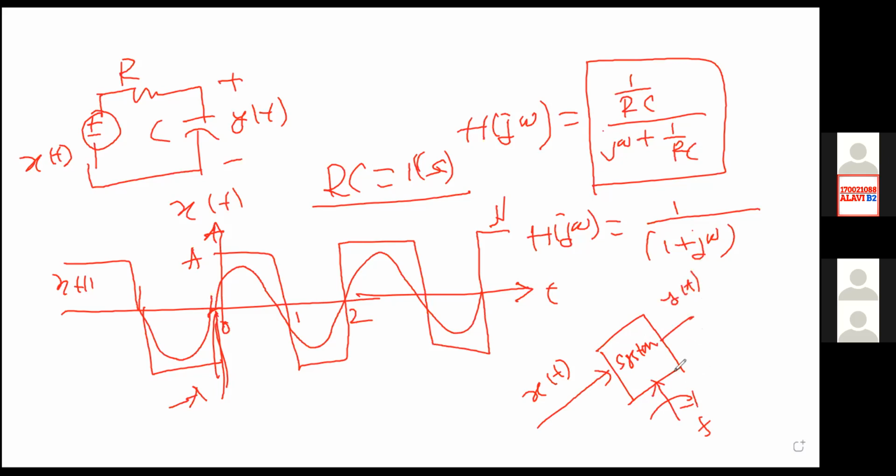If your system is tuned to frequency f0, then what will happen? You will get the fundamental sinusoidal wave, isn't it? Now, if your system is tuned to 2f0, and the 2f0 frequency exists in your signal, you will get an output sinusoid with lesser amplitude. Similarly, you can tune to 3f0 and again observe the output. If that harmonic is present in your signal, then you will have an output.